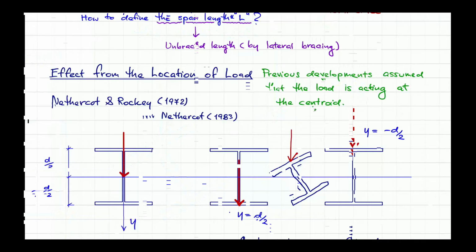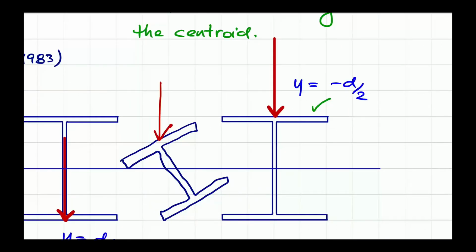this is your original configuration, and the deformed configuration looks like this. So when it buckles, again, it moves laterally, top moves more, bottom moves less, producing the torsion, and then the load is applied that way at that location on the top.